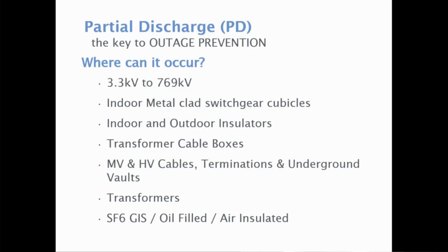By the physics, it can occur at any voltage on any insulation. Practically, we limit it to 3.3 kV or 4160. Below that, it can occur, but it's rare because those things tend to have lots of insulation compared to the voltage field applied. And the little bit that might occur is not going to lead to failure in anybody's lifetime. So the practical reality is below, pick a number, 2500 volts, 3.3, 4160, somewhere in that range, it doesn't make sense to do partial discharge.